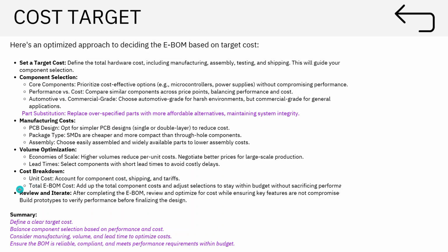Again, review and iterations. Whenever you design hardware, it is nothing like software where you just edit and run it. Here time is a factor. Once you have the PCB fabrication done, you do the PCB assembly of all the SMT parts, the electronic components. Once you have that hardware and you figure out there is something critical you missed, that cannot be sorted on that board, at least to have the testing done.